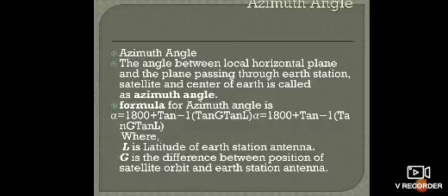It may look like 1800 in this formula, but it is not 1800, it is 180 degrees plus tan inverse of tan G upon tan L.